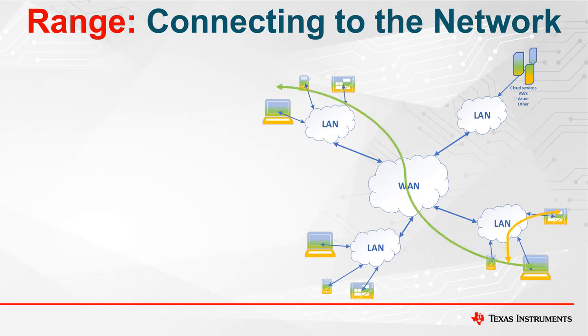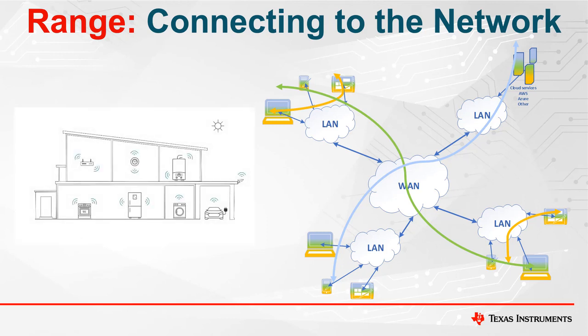Connecting to the internet over Wi-Fi is simple, as it can be achieved using the existing infrastructure. Most houses and offices already have Wi-Fi coverage through 802.11 routers, which would easily support another connection. The Wi-Fi range is heavily influenced by the environment, like walls and other interferers, and the operational frequency band, but the typical tens of meters range will enable direct connection to an existing indoor router. While other wireless technologies require the use of extenders or a mesh network, similar solutions are available in a Wi-Fi network, but are less common and probably will not be needed for connecting the new device.